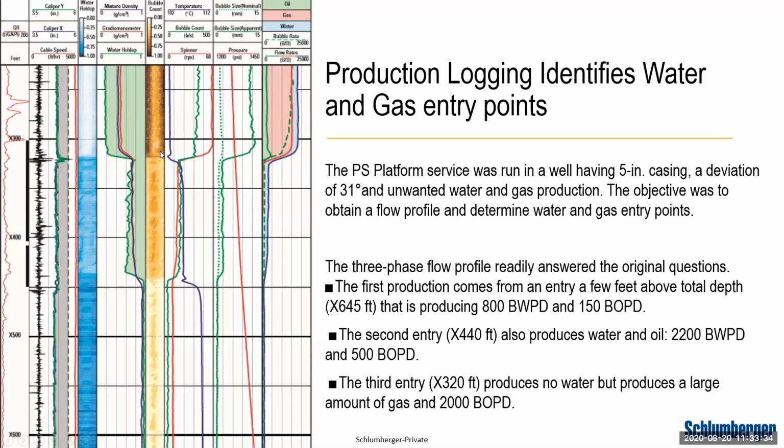The image that you see in brown is bubble count. So basically, when the image starts getting darker, that means that you have a higher count of bubbles of the non-continuous phase. So basically, you have more bubbles of hydrocarbon entering into the system. So I can see something very important here. If I look at my top perforation, it is not 100% active. I have that only part of my top perforation is active.